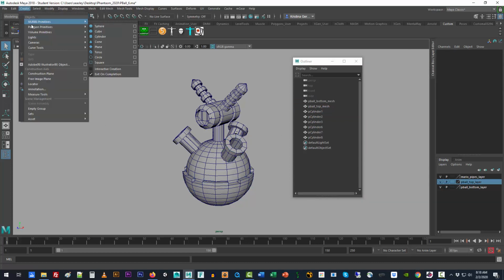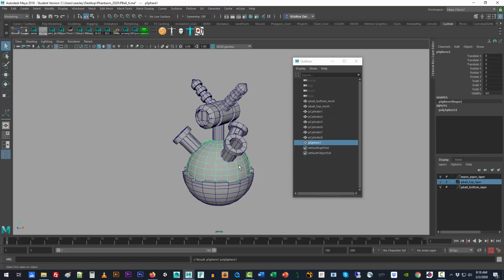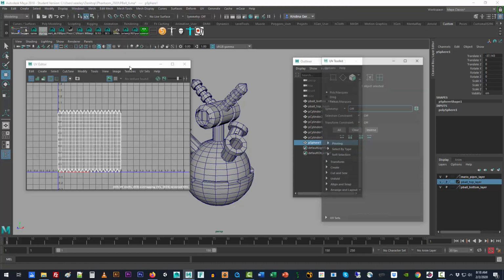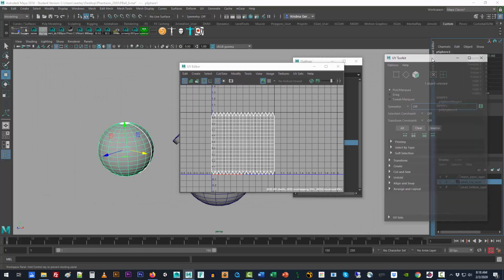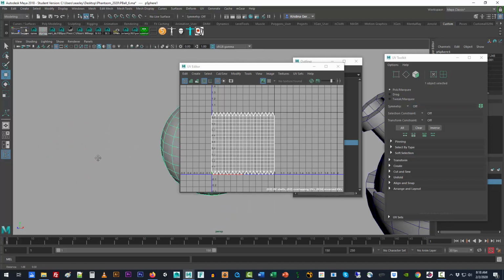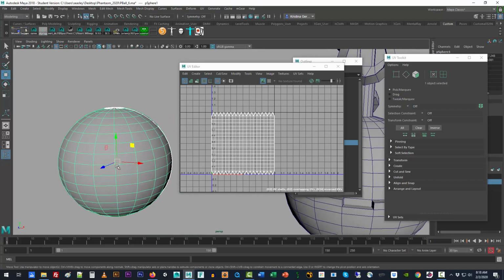First of all, think about the way that Maya flays things as a UV set. If you come in and take a look at the way that it understands the layout, you'll see that although you may see this as a sphere, this is still seen as kind of a flat square, meaning that if you were to put a texture on this object, Maya would set it up and sort of wallpaper it all the way through evenly, which means that this square, although it looks like the exact same size as that square,